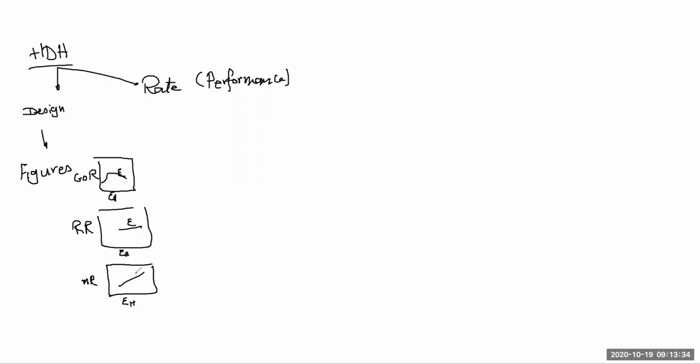So one is the effectiveness of the humidifier, one is the effectiveness of the dehumidifier. The problem should have the values of the effectiveness for humidifier and dehumidifier given to you. And accordingly, you would be able to know, if you are given the distillate flow rate, which is always the case. I mean, we say that we need to design an HDH system that can provide us, and the problem in the homework was saying 1 cubic meter per day.